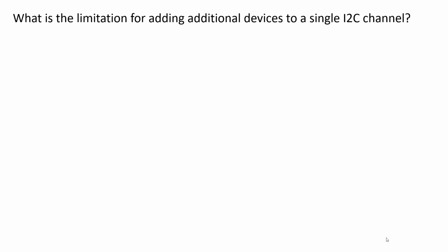And I think the ESP32 has multiple I2C channels, right? Buses, right? Because it has either 2 or 3 hardware I2C channels, and you have as many software ones as well. So there's 2 or 3 hardware I2C interfaces per ESP32. That allows you to partition your I2C peripherals on 3 different buses, so you can split them up.